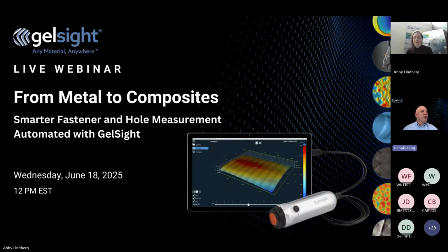Surface finish and edge quality, of course, are super important to fatigue life. When we think about things moving over the course of millions of cycles, all kinds of deleterious effects can be happening around that. So we can be creating cutting, we can be creating stress risers. We could have problems in the countersink that you might not have caught if you don't use a tool like GelSight.